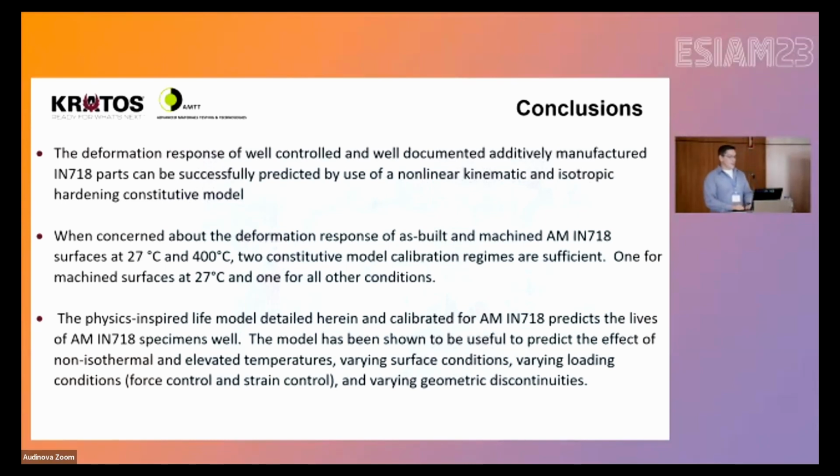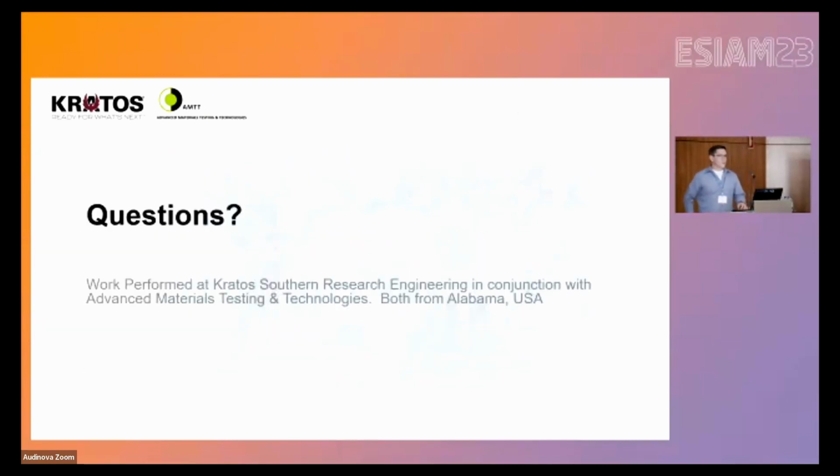Physics-inspired life model, detailed, not really detailed, sort of brushed over in here, and calibrated for this particular material, predicts lives of the Inconel IN718 well. Then the model has been shown to be useful to predict the effect of non-isothermal elevated temperatures, varying surface conditions, varying loading conditions, varying geometric discontinuities. And with that, I'll open up the floor for any questions.